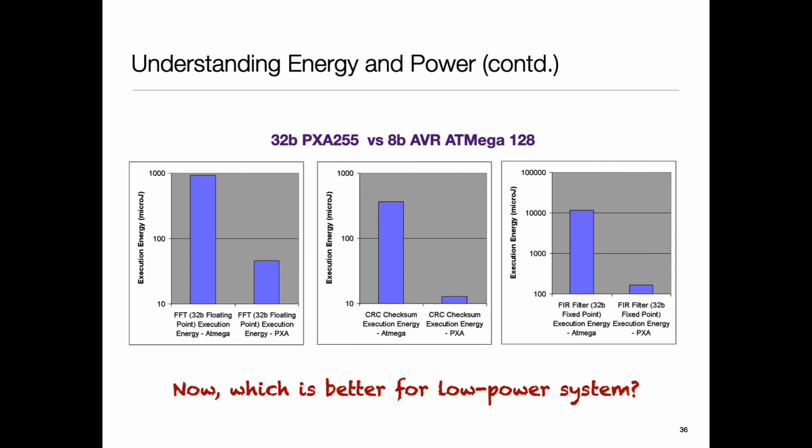So which one should I pick? If my system was designed for just keeping an eye on the world and doing something simple, clearly I'll pick the microcontroller. If on the other hand it's designed to do some hefty computation, clearly the bigger processor benefits. You would generally see this story play out again and again. If I have to send a bulk file, Bluetooth low energy is awful, so I'll pick Wi-Fi.